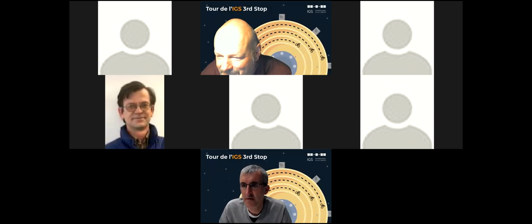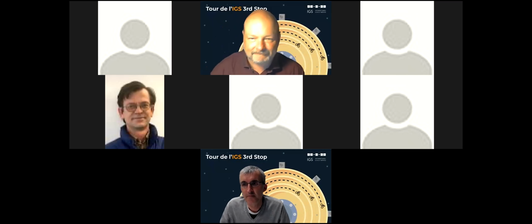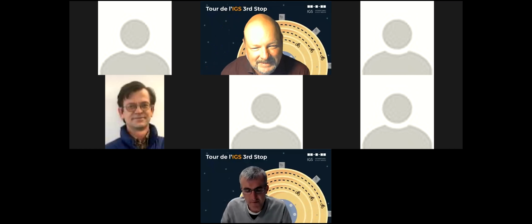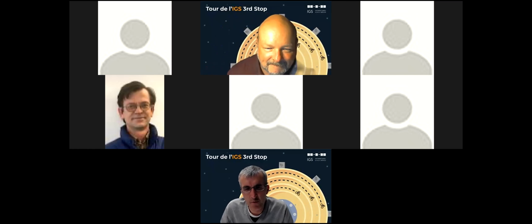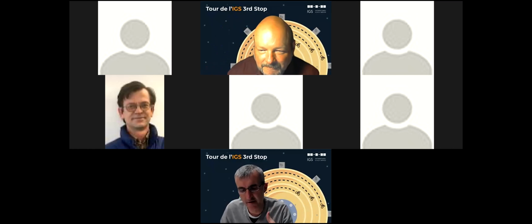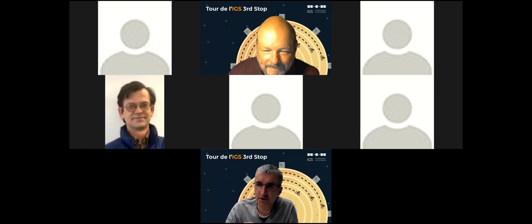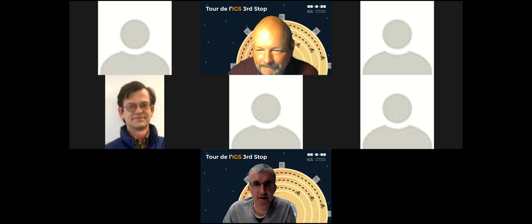advantage of VMF3 mapping function very significant compared to using VMF1, in your opinion? Thanks for the question. Well, in terms of the mapping function part, I would say no. I do not see a clear advantage of the VMF3, but the advantage of VMF3 is that it has a 1 × 1 degree resolution, and VMF1 has this 2.5 × 2 degree resolution, and actually it's an advantage for the zenith hydrostatic delays.